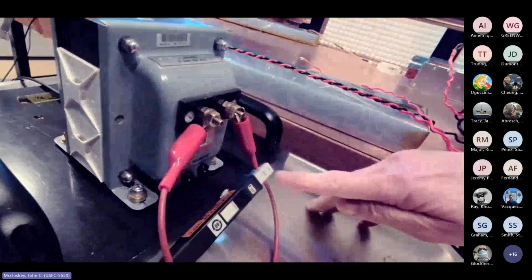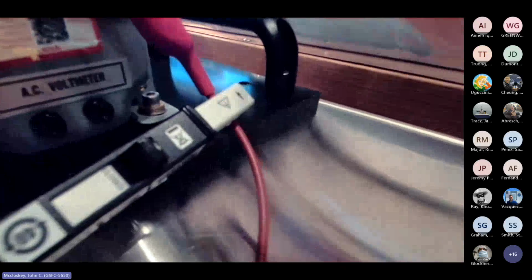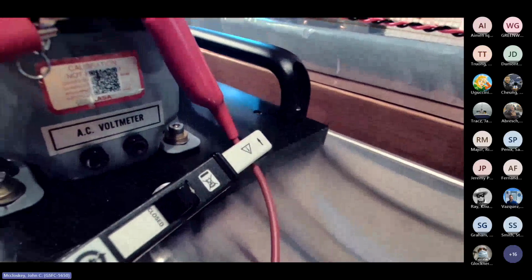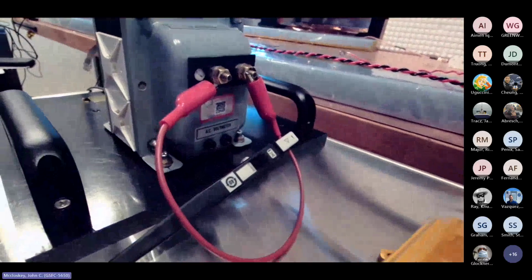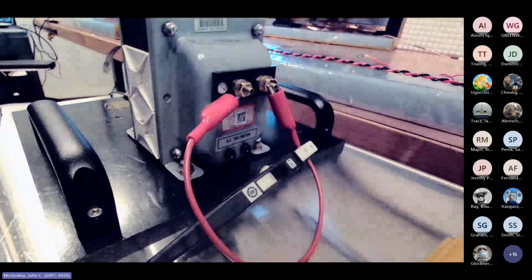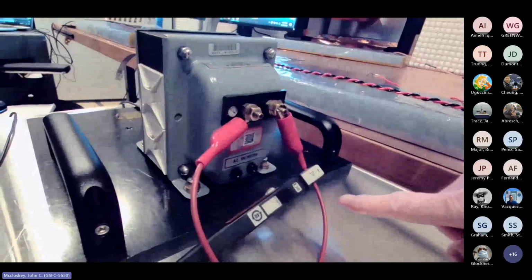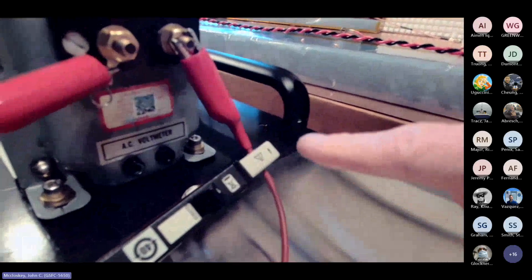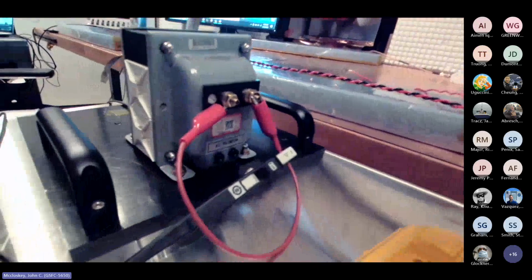All right, and you can close up on that. The arrow on the current probe is in the direction of positive current flow. Doesn't really matter for what we're doing here, but when you're looking at the conduit, it's good to pay attention to what direction you care about. When we actually look at the relationship between voltage and current to look at impedance into the unit under test, that will be important. So it's good to always pay attention to the direction of current flow, that it's in the direction you're interested in. But for this step, we're just looking at magnitude.